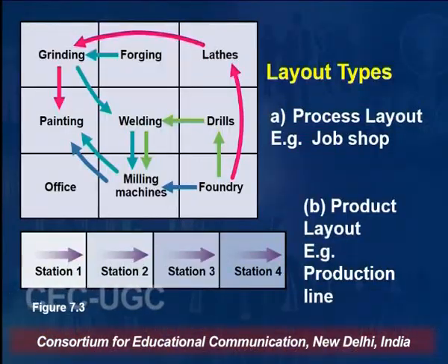So you need higher inventory of raw materials because you need to work on different kinds of products, different types of variety, because your layout is with respect to processes, not with respect to products. And each kind of product which you have to manufacture may follow a different route, may follow a different pattern of manufacturing, etc. So let us see this diagram of layout types.